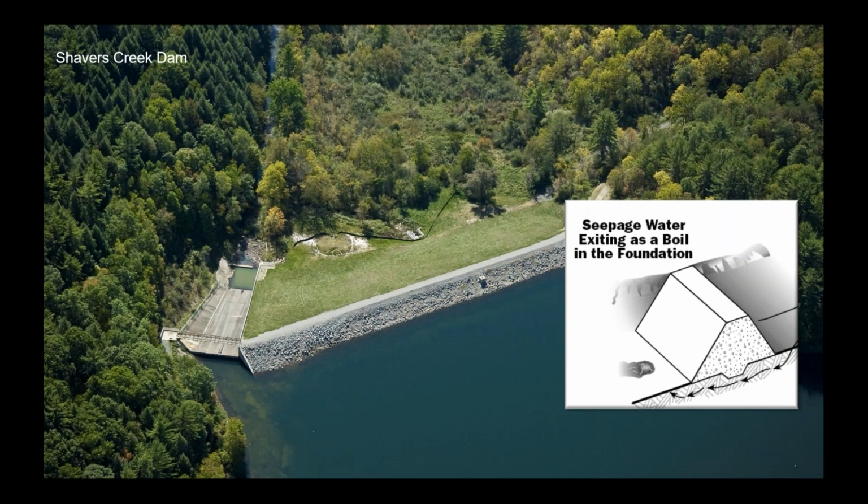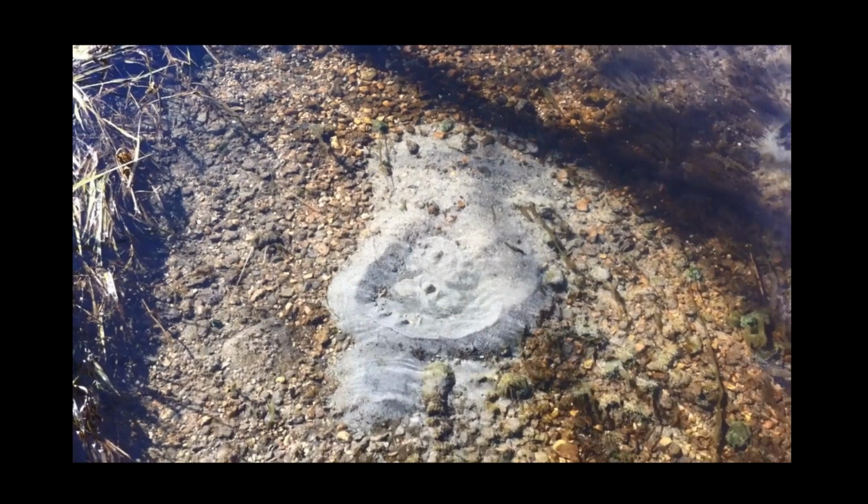Also, when you're inspecting the embankment, you need to inspect beyond the embankment. Here we're looking at the toe, and because of confined layers or concentrated seeps, we talked about that a little bit looking at the dam basics, it's possible to get a concentrated seep at the toe of the dam and get what is called a boil.